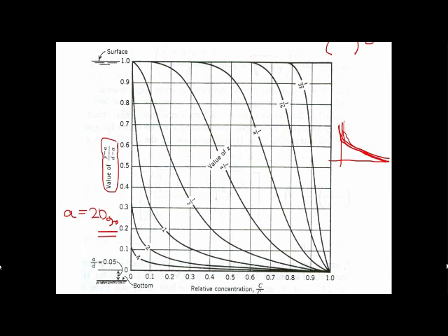For example, in this diagram, Rouse determined that the thickness of the bed layer is equal to 0.05 multiplied by the depth of your water, the water depth. Okay. So C here is the concentration at any profile, at any depth. And then Ca here is the concentration at the bed layer thickness.